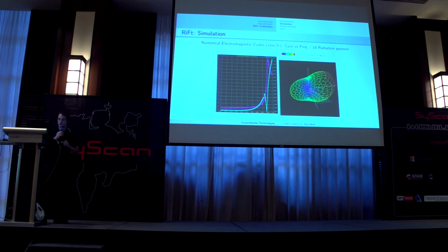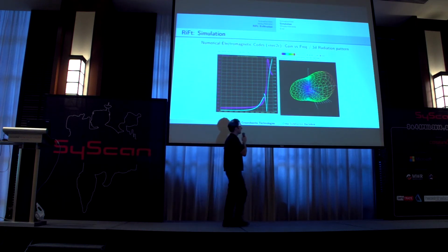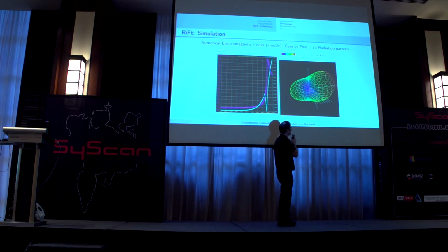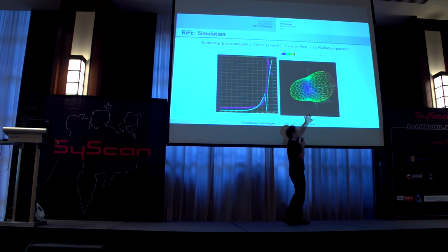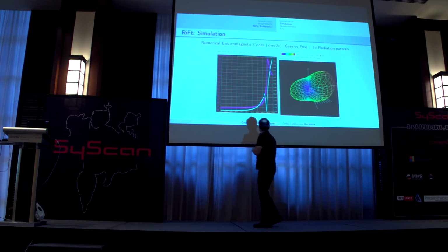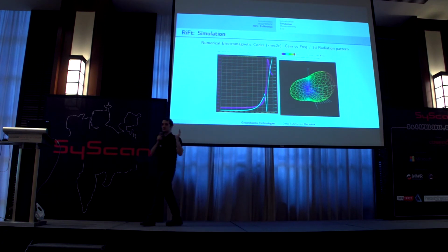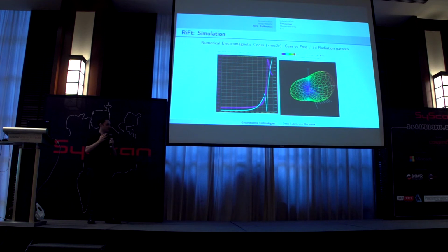Of course, we can run a simulation of the PCB, how the field looks, the radio frequency field, the power field. We can see something very peculiar here: if we don't use a single PCB but use 4 or 5, we actually use 8 because we have 8 LEDs. So the field is actually directed because it looks like a Yagi antenna. It's like some kind of Yagi formation.